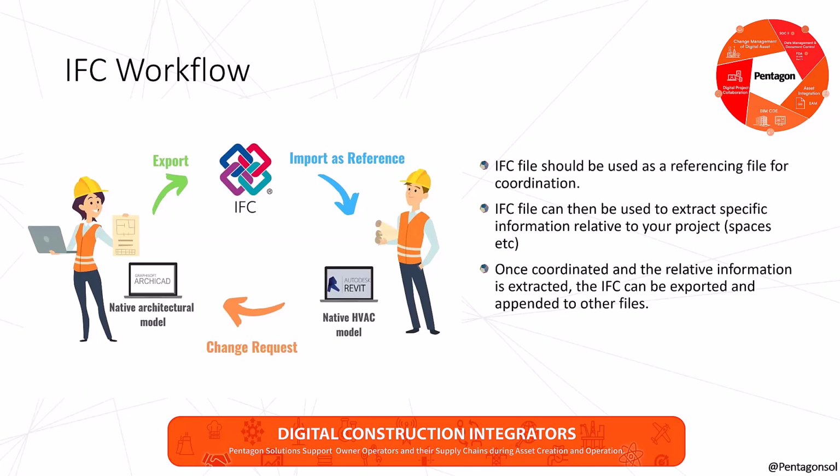Once the information has been extracted from these IFC files, I'll be able to populate my project with that information and then create an IFC export from that, allowing me to append these models for coordination through the likes of a different viewing tool. So just as a bit of an example, I've prepared a video on this.